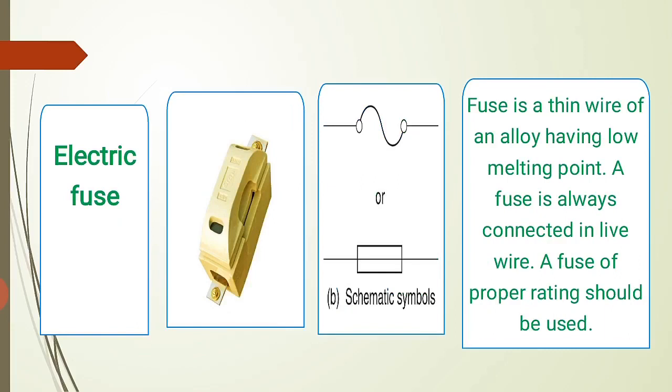A fuse is always connected in a live wire. So it means when current is there, at that wire only a fuse is connected, right? A fuse of a proper rating should be used.